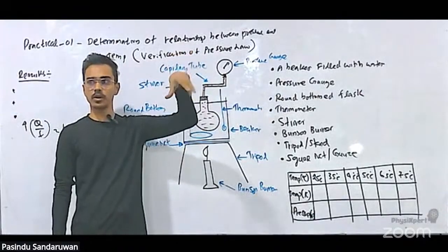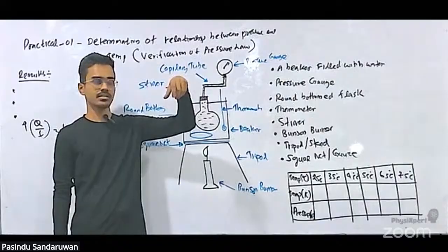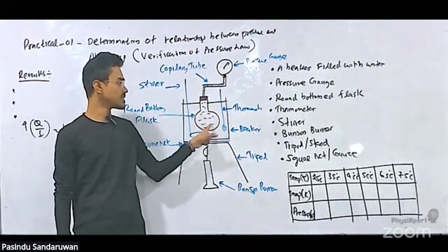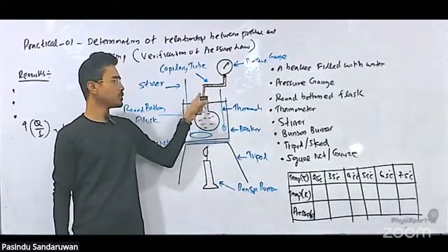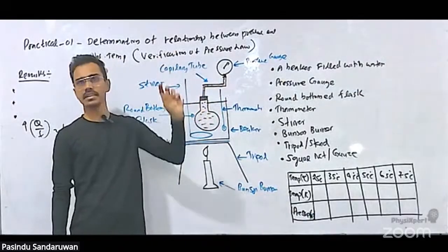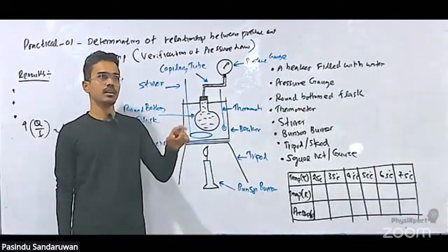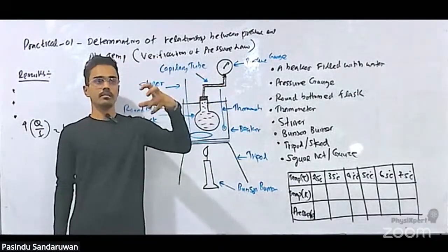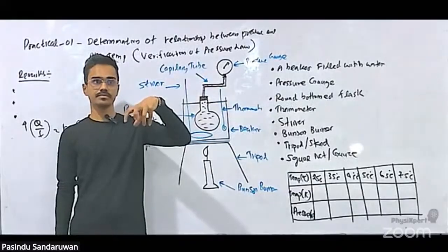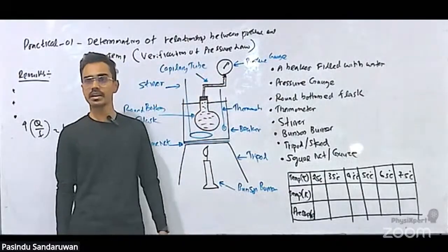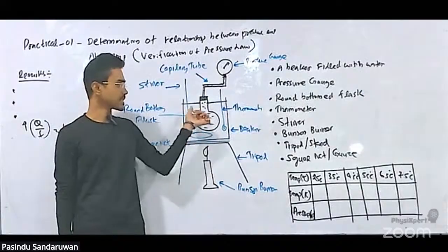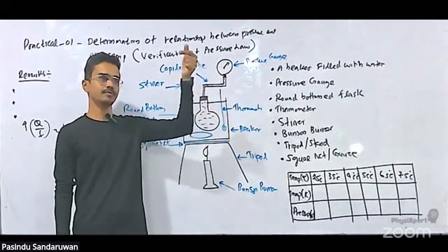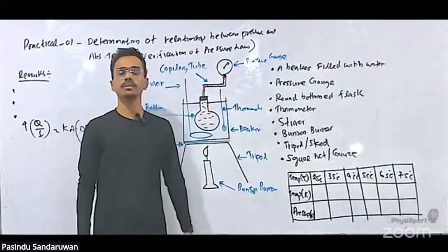That is our allowed limit, 1%. So we choose a capillary tube here to minimize the percentage error, and we neglect it while staying inside our limit. With a big tube we cannot neglect it. With respect to the volume inside the flask, this should be negligible. To serve that purpose, the capillary tube is used.